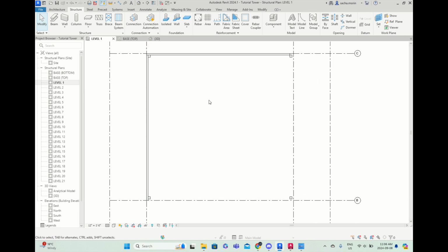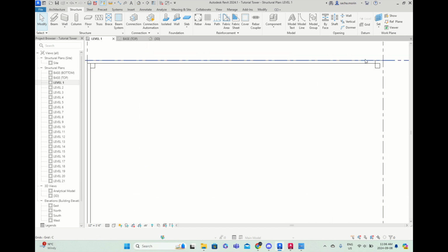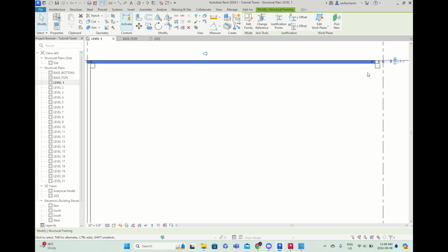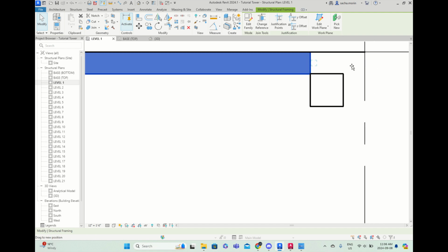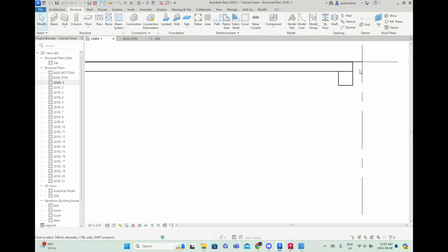Just as another little bit of context, whenever we're making our perimeter beams, the current philosophy in how we make the perimeter beams is that any given beam will only extend into one corner. So you can tell this beam here, this top beam, it extends into the corner here. Therefore, I will not extend it all the way down. I'll only bring it to the column such that the other beam will go there.